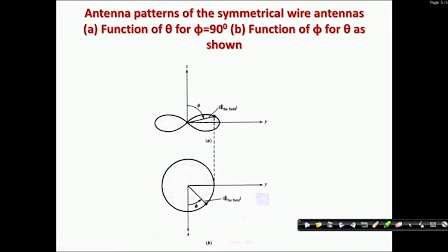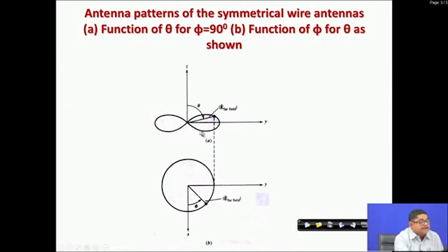But before that, in this wire antenna discussion, we want to point out one thing. If we look at the wire antennas that we have seen till now, the wire antenna pattern looks like this. You see that in the E field or in the theta direction, we have a directed beam, but in the phi direction or in the azimuthal plane, we have a non-directional pattern. Now, that has some problem. All the wire antennas that we have seen are symmetrical, symmetrical from the feed point of view, and for that this is natural that in the azimuthal direction there will be no directional nature in the radiation pattern.